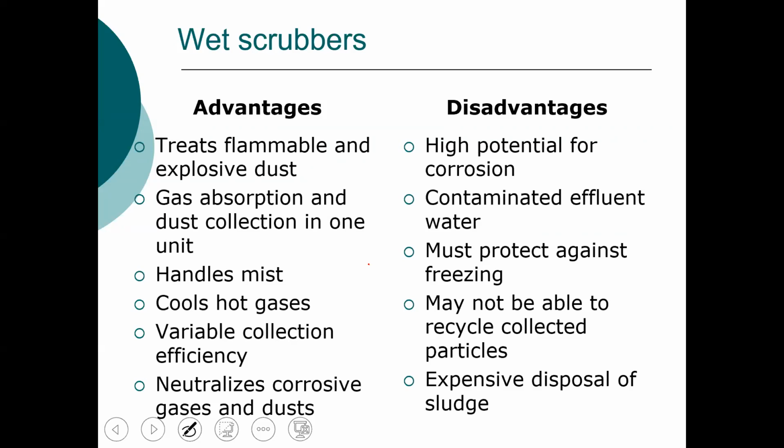Unlike the other processes that we've talked about, you can achieve gas absorption into the liquid and dust collection in one unit. So for instance, as I showed you with the boiler flue gas treatment, that can be used for SO2 removal. So you're looking at a gas removal, and you're also looking at particulate removal.